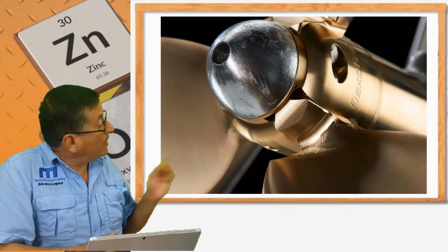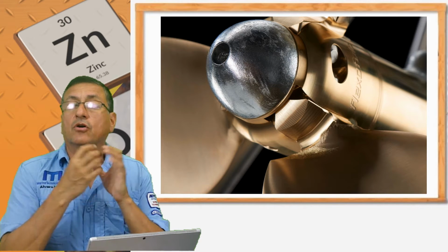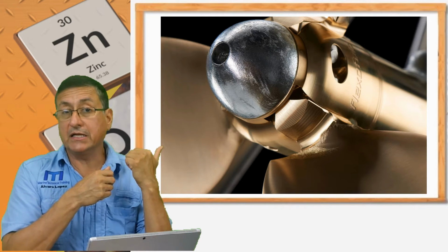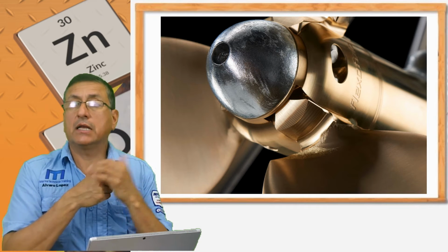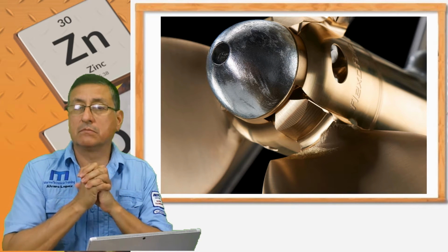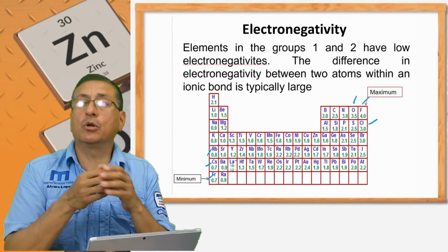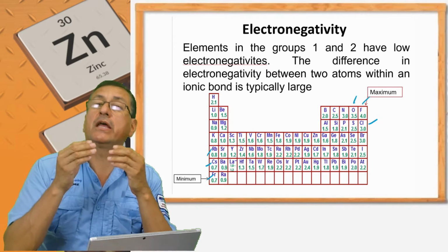The zinc at the end of the propeller is attacked. The oxygen attacks the zinc, and the propeller is protected. The propeller in that case is more cathodic, and the anode at the end of the propeller is more anodic. It's the sacrificial anode because it's less noble. That's clear? The less noble metal will be eroded.